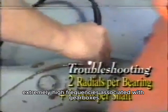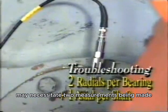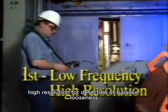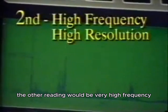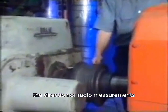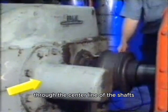The extremely high frequencies associated with gearboxes may necessitate 2 measurements being made for each sensor location. 1 measurement would be low frequency, high resolution for detection of balance, looseness, misalignment, and bearing problems. The other reading would be very high frequency to 3 or more times the gear mesh frequency with high resolution for determining gear condition. The direction of radial measurements should be in the line of force of the gears, through the center line of the shafts.